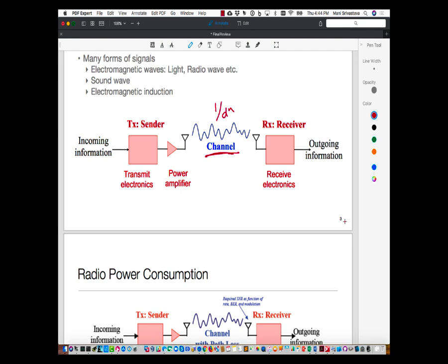Complicated radios are pretty good on an energy per bit basis, but that manifests itself only when you are sending lots of data. And so Wi-Fi actually, if you compare just the energy per bit number, I mean, Wi-Fi radios are now what, gigabit per second or 500 megabit per second. So if you compute their energy per bit, it's actually much, much better than the Zigbees and the Z-Waves and all. But it is only if I'm able to keep them pumped in with data.